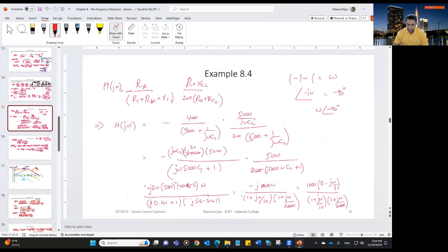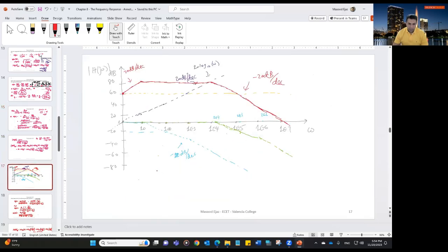And then you're going to enter your poles, so 10 and 20,000. Once you enter those inputs, your project should create these dotted lines to show the Bode plot corresponding to each factor, and then add all of these to give you the Bode plot. So that is the project, of course.